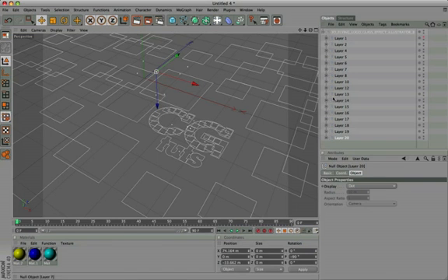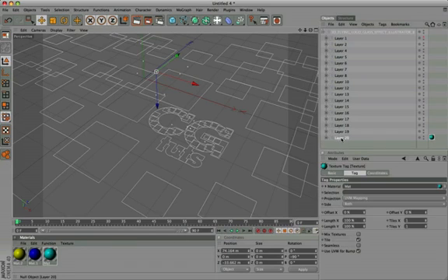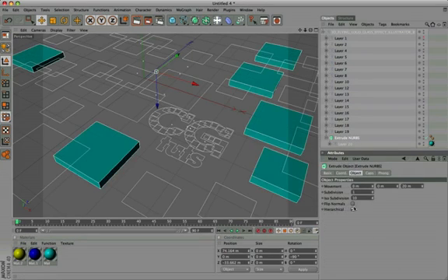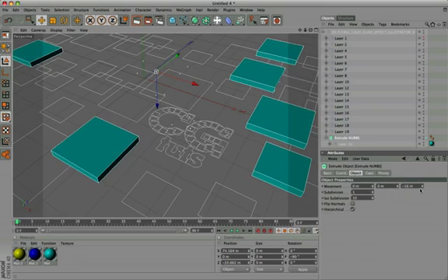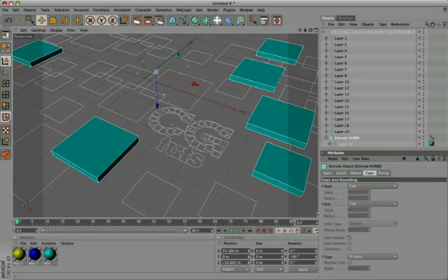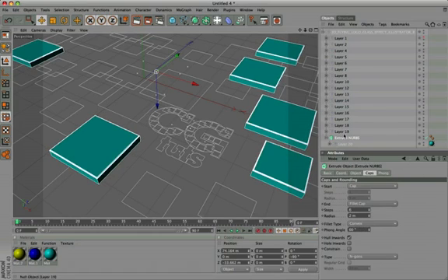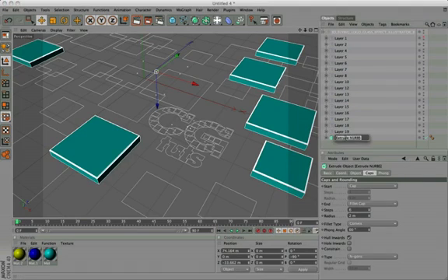I will tell you a trick. Drag the cyan material onto layer 20, holding down the Alt key, while applying the Extrude tool. The tool will be applied to the selected layer. Check Hierarchical, and enter the value 16. Fillet caps, only at the end, with step 6 and radius 2. Rename this layer Extrude Cyan 16.